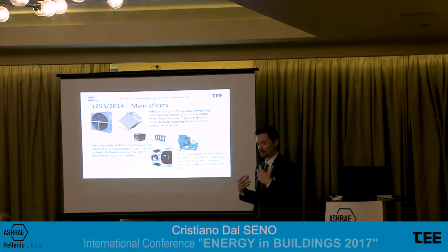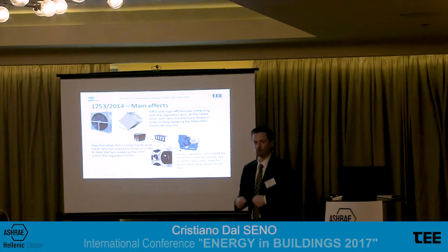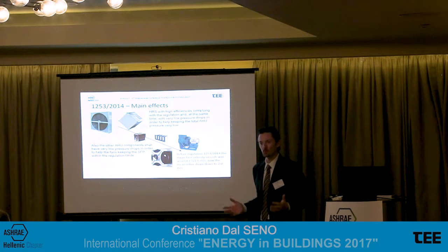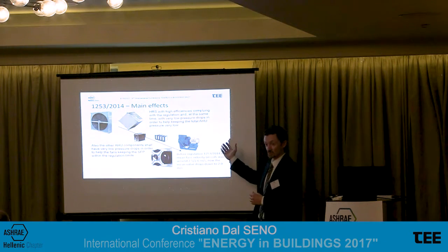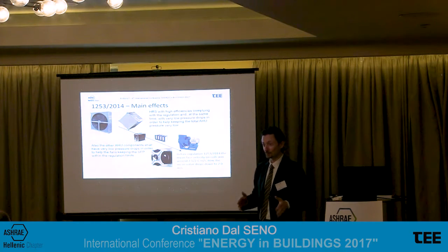Many consultants came to me saying, Cristiano, but if I write a letter stating that it is a special installation in a historical center in the center of Rome, I have no space where to install such a big air handling unit. Should I consider for this special case the opportunity to remove the limitations given by the eco-design and use the typical old way to design air handling units? No, it's like the catalytic discharge for the gases of the car. You cannot write a letter and say I don't want it because I don't need it, I think that I will use my car one day per year, so why use it?